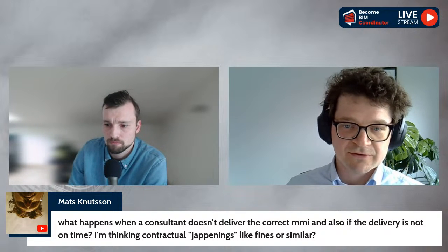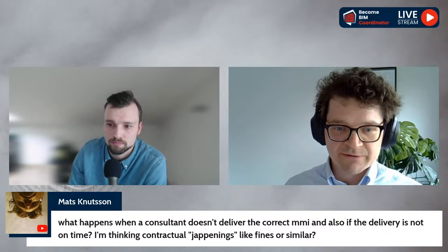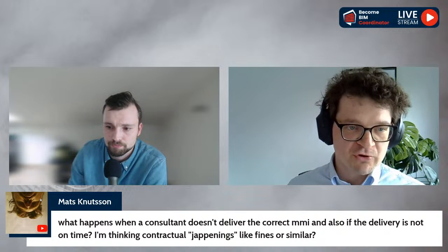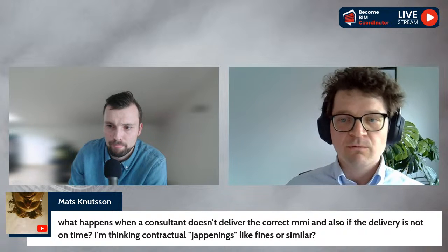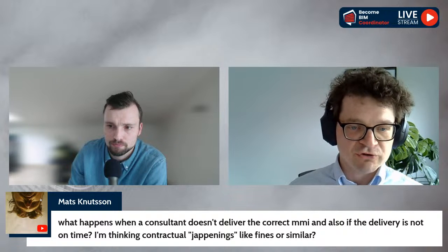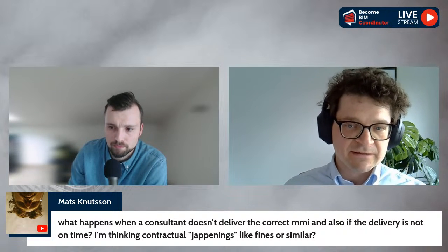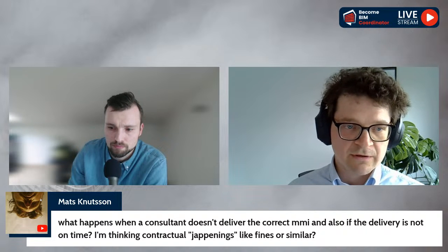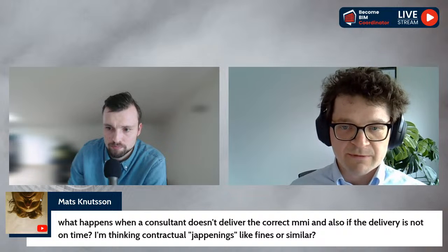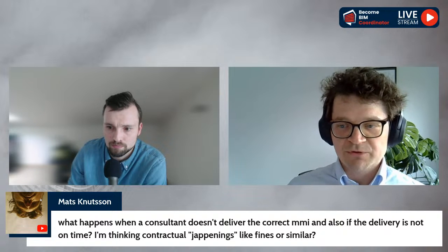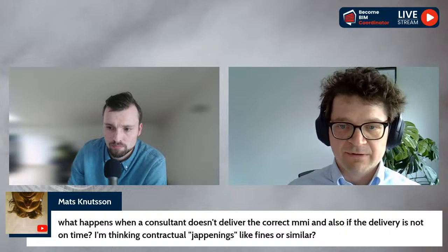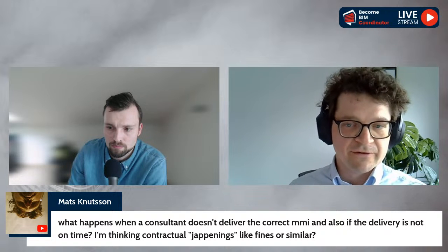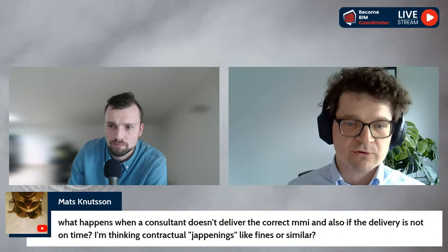Yeah, the contractual fines are also a little bit out of my responsibility. But when I'm controlling it, I know how many objects. Solibri gives me the result of how many objects, in which discipline, are not ready in that control area, and I send it as a BCF file as an issue. So, dear architect or dear MEP electrical designer, these are the objects that are not coded, and up until now they have, for example, MMI 300, and they should have 350 or 400. So please correct them. This is the check I also do.